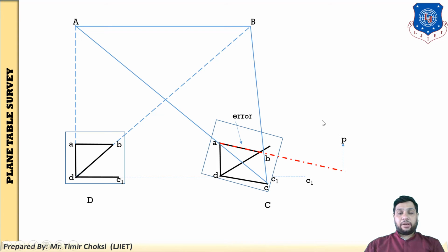Then after doing the orientation as well as rotating the plane table, you have established the accurate point on the drawing sheet. Then you transfer it on the ground using the U-fork with plumb bob. So this is the two-point problem method. Okay, students, don't get confused. You are watching the video, so also refer to the book, the reference book, and two to three times you will understand this method clearly.